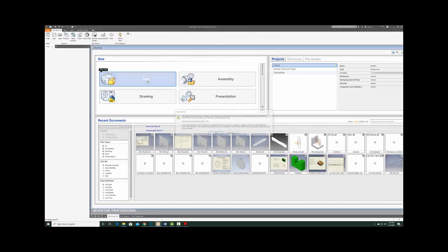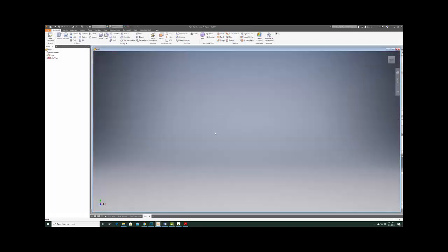So I'll start by creating a part. Just click part right there. Say OK. And then I'm going to go ahead and start a 2D sketch. Okay. And by starting a 2D sketch, it brings up 3 planes. It brings up a YZ plane, an XZ plane, and the XY plane. Now I kind of think in the XY world, that's just where my mind goes, so I typically like to click on the XY plane. But you're welcome to do whatever you guys want.